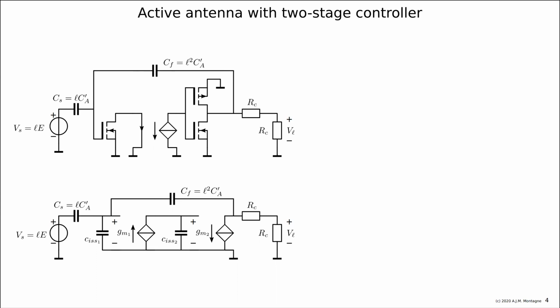That's the idea. And for the bandwidth design of the amplifier, the product of the poles is decisive, and the sum of the poles has more to do with the stability. Of course, both poles should be part of the dominant group of poles if they want to contribute to the bandwidth. That can always be checked at a later stage. So let's do this. You can make a loop gain expression by selecting either GM1 or GM2 as loop gain reference, and you find something like this.